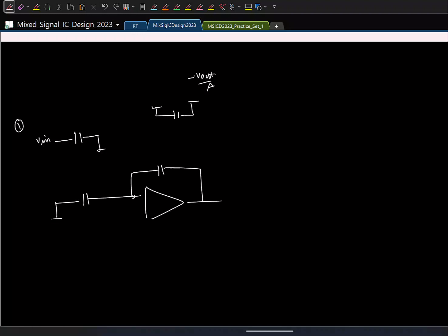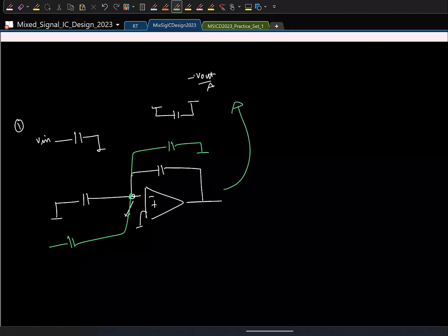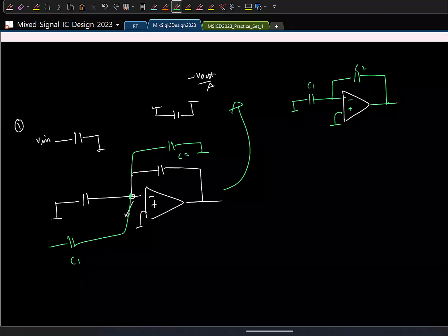Now I can get this voltage error. So with respect to this voltage, I will be charging another set of capacitors like this, right? And in this phase, basically I'll do charge transfer with respect to the new capacitors. This is, let us say, C1, C2. So the previous thing should be connected to V. That's all. So this is C1 hat, C2 hat. C2 should be recharged. So this is, let us say, phase phi 2.